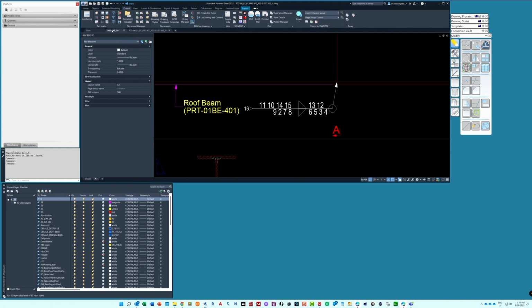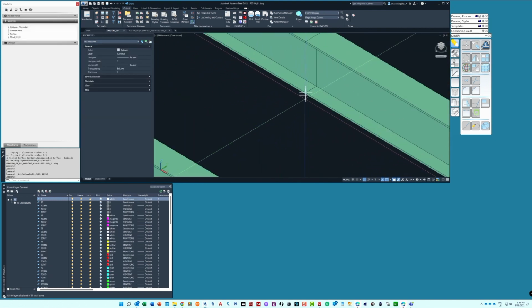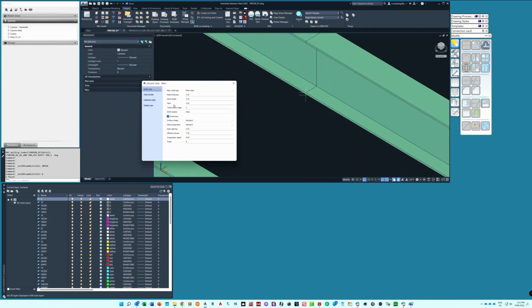Let's go back to our welds and put in some more realistic numbers to have a better idea of how that would actually show up if you use these numbers. So a weld thickness for a fillet weld, 6 would be normal, a weld length of 50, a pitch for weld of 400, our groove angle, we'll put in there 30 degrees.